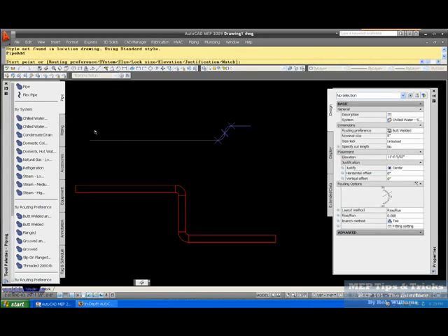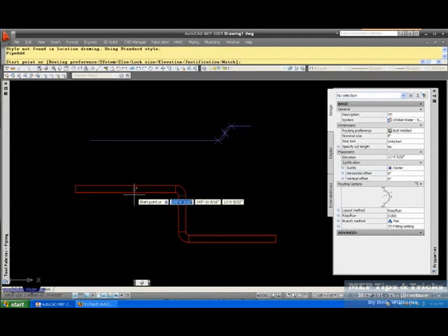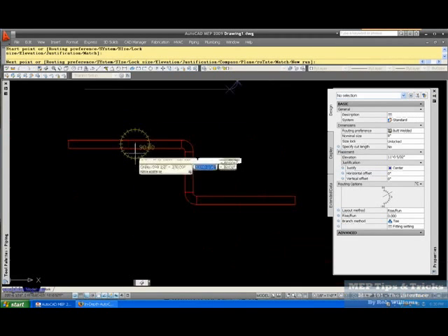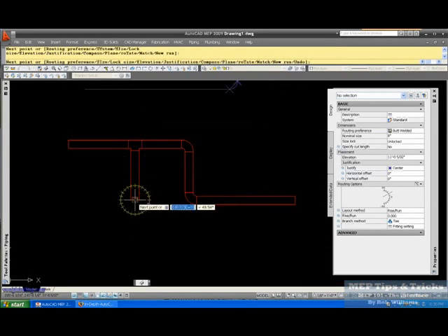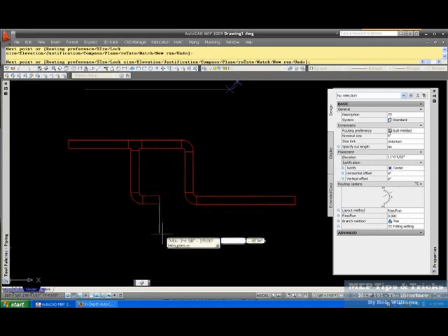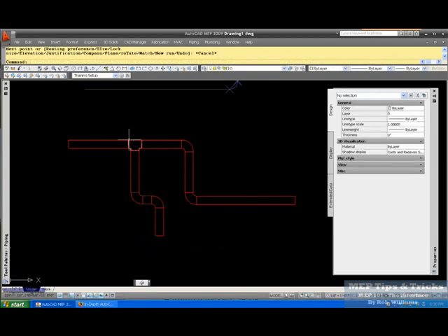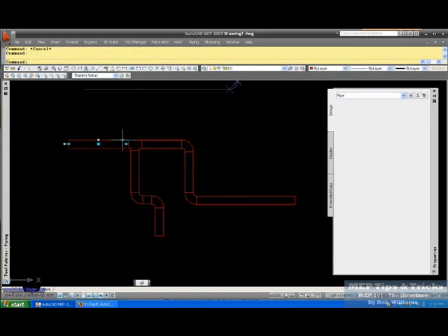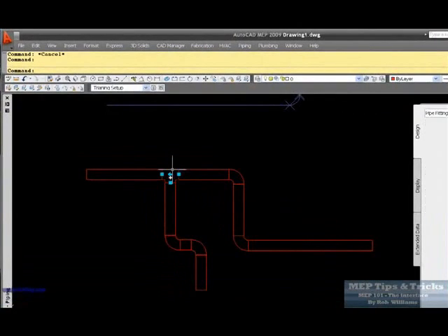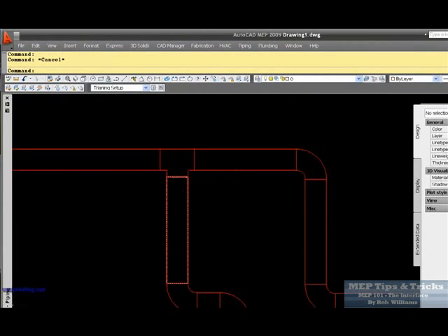So you wanted to connect a piece of duct or pipe to that and draw off of this, and it won't let you draw that chill water. It's going to draw exactly the same layer that you're on, so you're not going to have a bunch of different layers. It automatically knows to connect that, and it'll set you up.